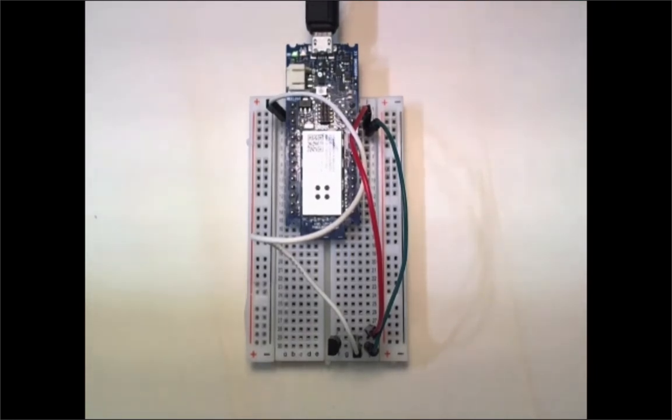So a standard Arduino has a resolution of 10 bits, so it represents voltages with a 10-bit long number. This Maker 1000 actually has the ability to go up to 12 bits, but for uniformity with the other Arduinos, I'm using just 10-bit. So once I have a number between 0 and 1023, I have to convert that into millivolts. So you can see here, I'm calling voltage equal sensor value, which is the number I've just read from the analog input.